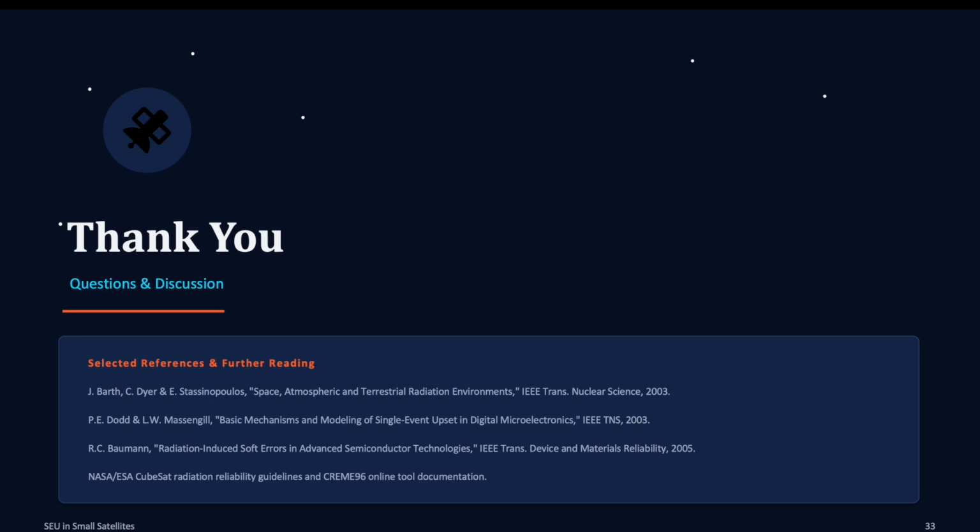I have a comment actually. You talked about how to check the single event upset probability. What we did, actually, is we had some in-orbit data before, starting from 4U2. You should check those publications. If you didn't have a reset capability, then we added the 24-hour reset to our satellites.